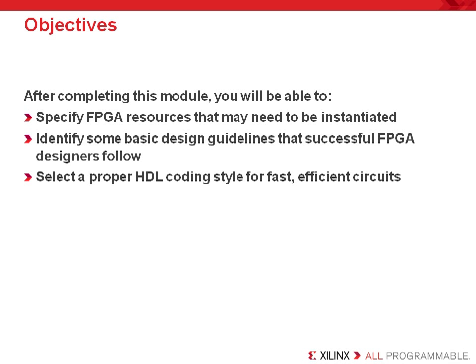But the key thing is that many new customers are disappointed that they are going to have to instantiate some of the most popular FPGA resources into their design. This is now pretty much standard operating procedure in the FPGA industry. What I mean by that is that most customers are prepared to create highly optimized cores with the Xilinx core generator or the Xilinx architecture wizard utilities, and are then going to have to instantiate them into their HDL.